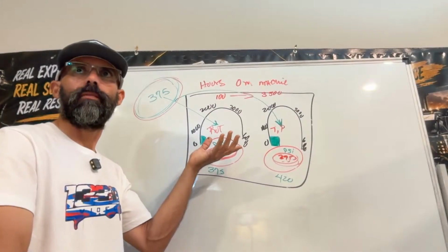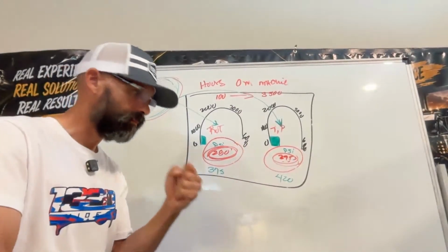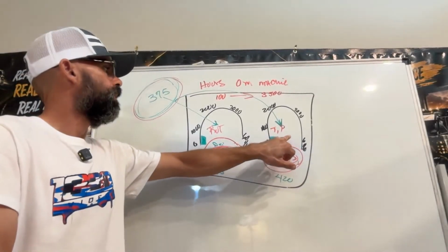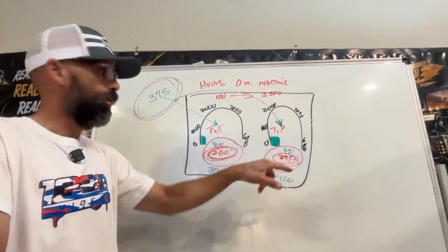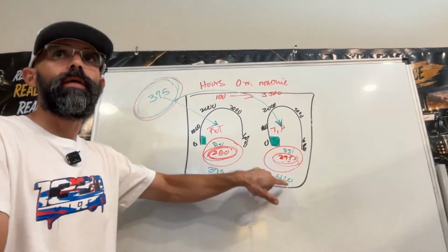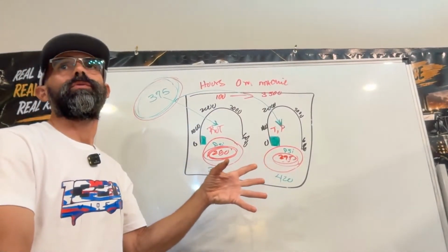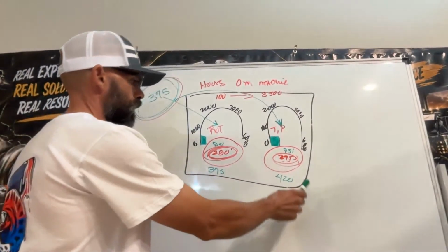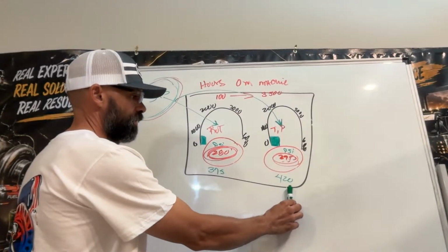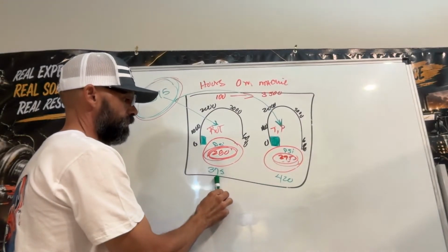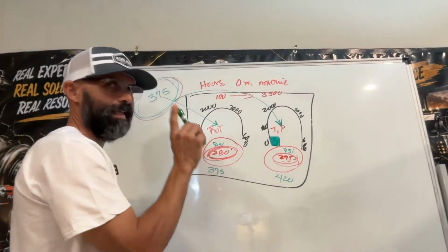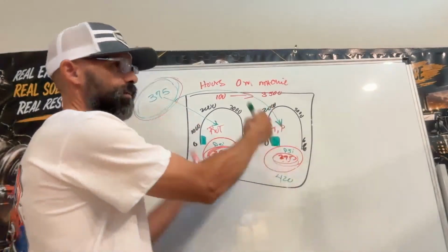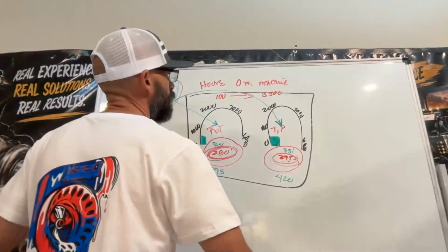Simple, right? But you put the gauge on the shuttle valve for the pressure transducer of the thrust and pullback, and you see the same pressure that it is telling you on the display. Okay, then it's not a faulty pressure transducer. So how can I lower this pressure to be the same as this pressure when you only have one relief valve on the pump for both systems? Simple. Let me erase this.